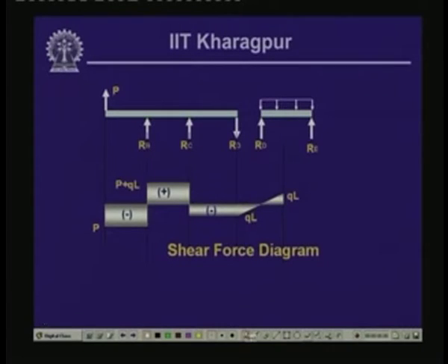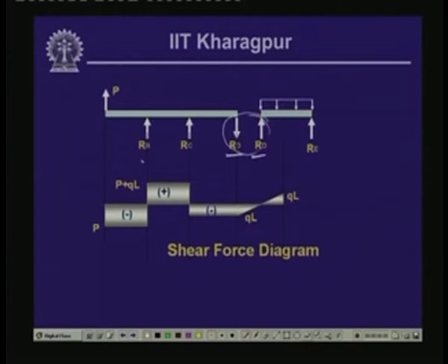Now, this is the diagram plotted, but you see that this particular beam has been split at the articulation, and we have introduced one reactive force RD over here. Now, these two forces, please note, are balancing in nature. That means one beam is getting supported over the other and transferring the shear force here. So, it can resist the shear force, but it rotates when it comes to bending. Now, the uniformly distributed load acting over here is Q. This is of length 2L, and all these segmental lengths are L.